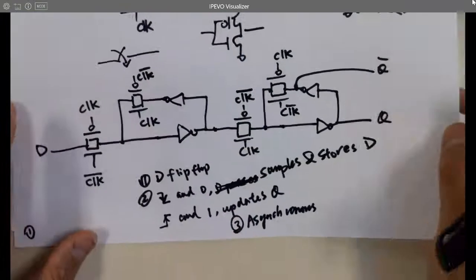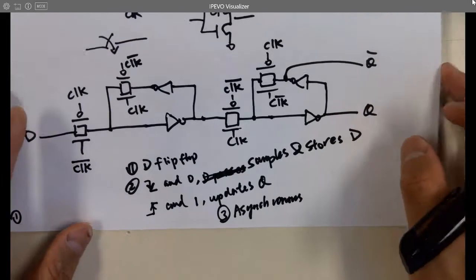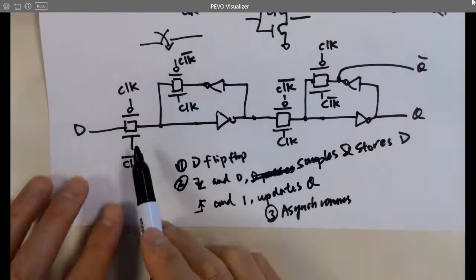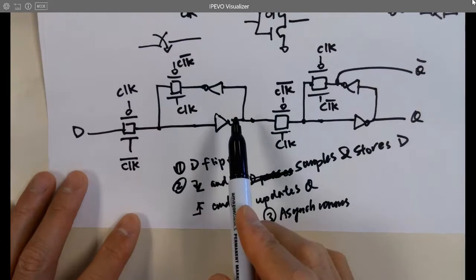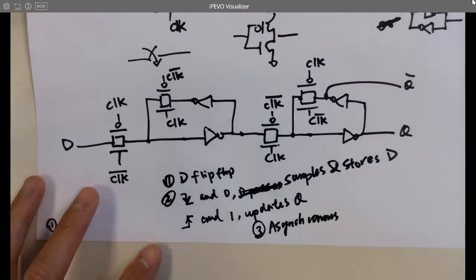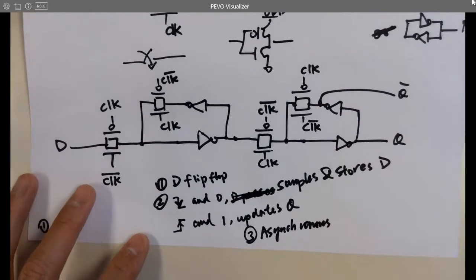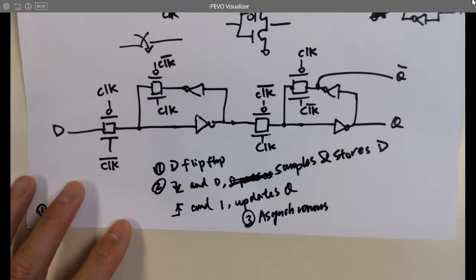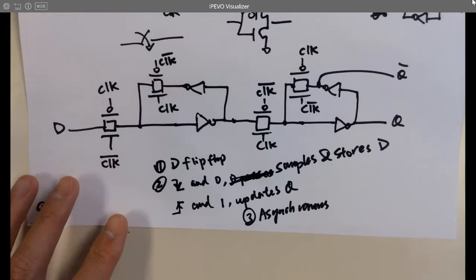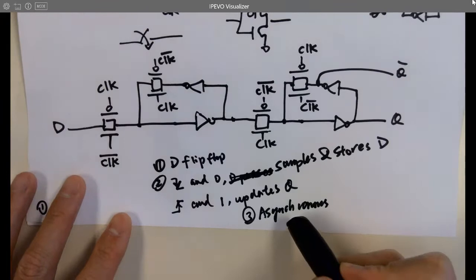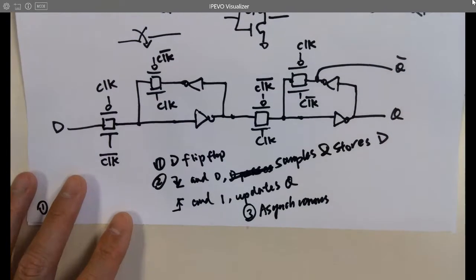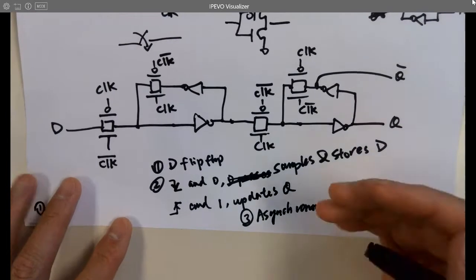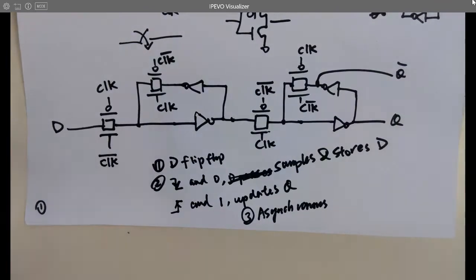Yeah, but we prefer synchronous rising edge triggered or falling edge triggered, right? It's very accurate. It only samples at the edge. But with this one, whenever it's open, it's going to keep sampling, which is bad. You want to only sample at the edge because the signal can change really quickly, right? When you want to sample it, just sample it. You don't want to make any changes to the sampled data. So in order to have an edge trigger, you have to have two different clocks, and that's asynchronous, right? But the two different versions we are going to use are synchronous, edge triggered, which is awesome. Just sample, done. So whatever D changes, it's not going to affect anything.